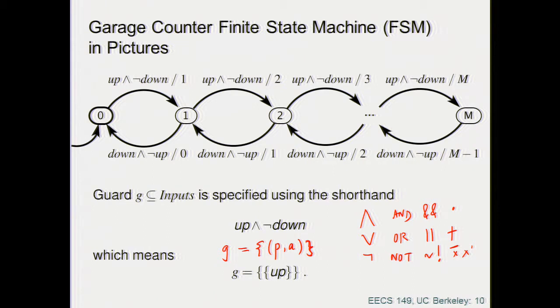The interesting thing is that in a linear system, or any system describable by a first-order differential equation, to find out what happens to your system in the future, the only thing you need to know is where you are now plus the input. So you don't care about what happened 2 years ago, because all of that is in that state. That state is a summary of all the information I got.